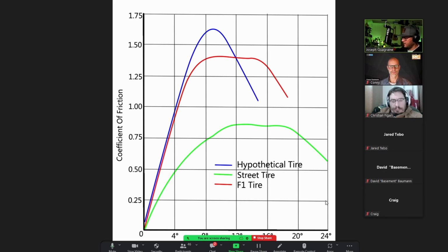Well, the part that's stuck to the track can't turn because it's stuck there, right? So the tire twists a bit. And then imagine you start rolling the tire like that. Well, the direction that the tire is rolling and the direction of the tread that's stuck on the track, there's an angle difference there. They aren't heading in the exact same direction. The tire is being twisted. That angle is called the slip angle.